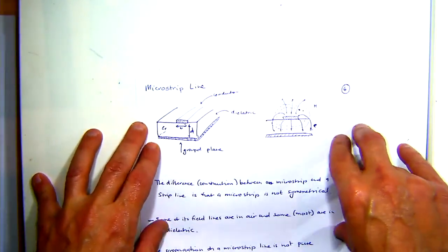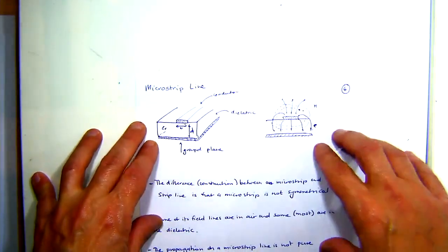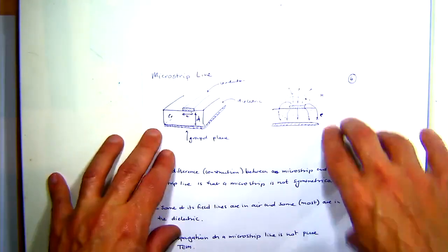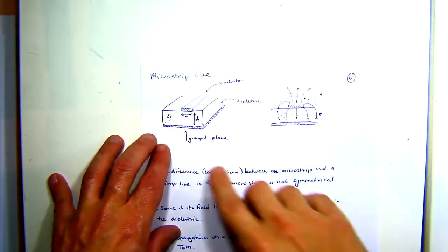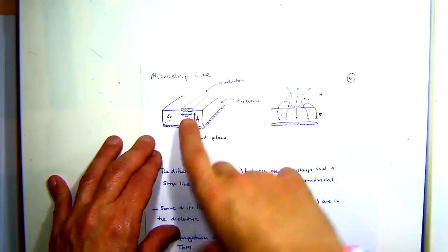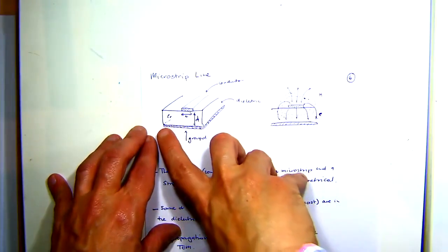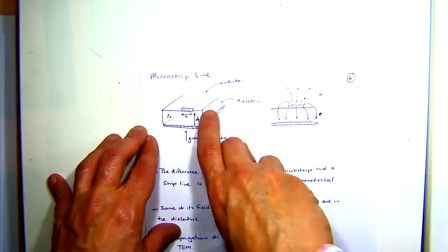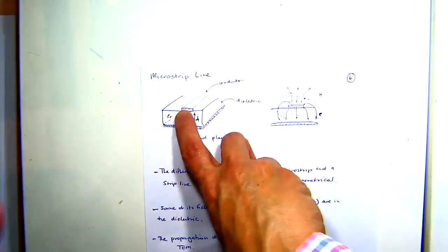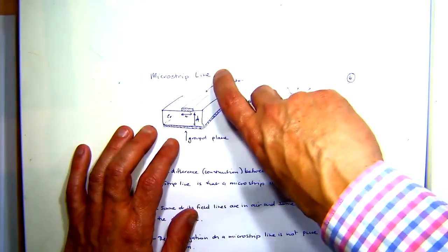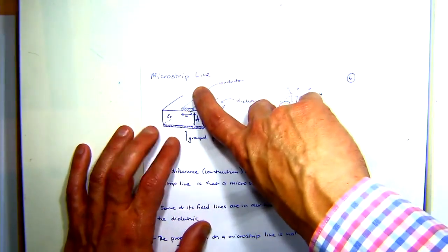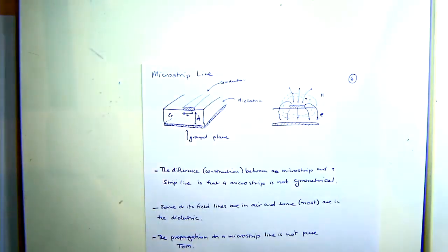The other type of line or waveguide that we should be very familiar with was a microstrip line. Essentially, a microstrip line is a waveguide which has a ground plane. It's got a dielectric slab, which is just the dielectric material, and a conductor on the top of it, right? The reason why we do that is, ideally, if we wanted high performance, we would put it in between the layers, and we'd put 2 ground planes, and we'd get nice TEM propagation.